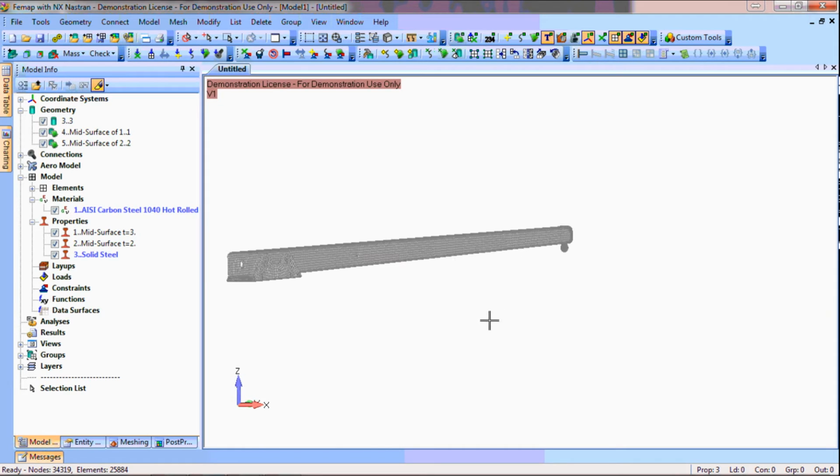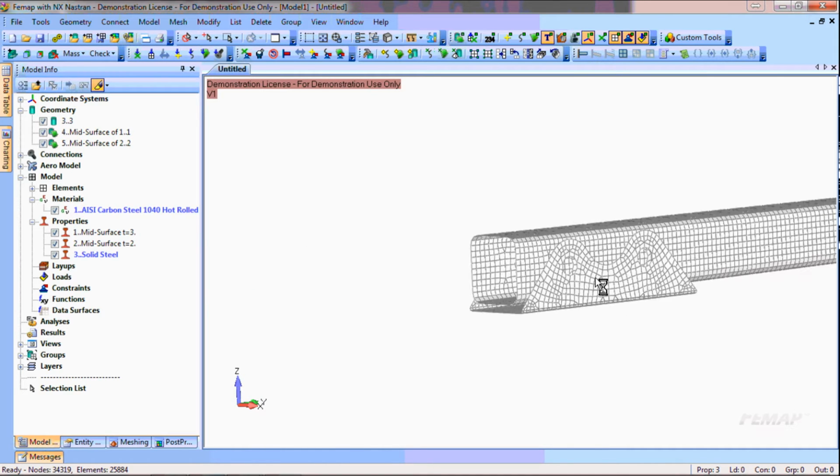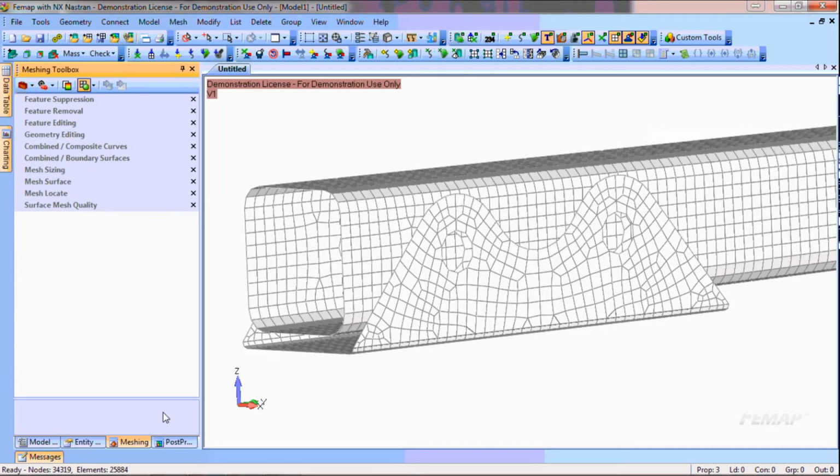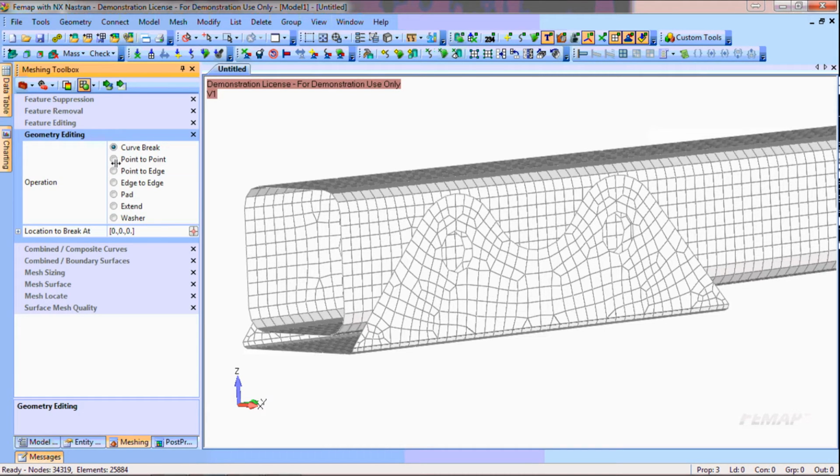Now if we come back up to this end, I need to connect the beam and the end plate, and often what happens in finite element models is the bolts get connected to the edges of a beam or the edges of a hole. Now this is not ideal. Femap gives you some extra tools in order to create effectively washers to share the load of the bolts, and these washers should represent about the diameter of the size of the fasteners.